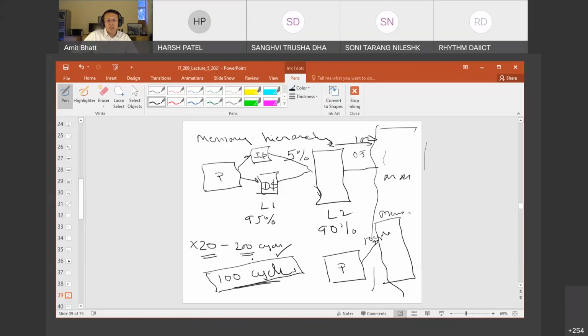So usually real-time processors are embedded processors, right? And then, which programs are going to be executed, they are fixed. For example, in your airbag, the program is fixed that, as soon as you get the signal, you send another signal to these chemical bags, and there is a small explosive charge in that, which would explode. And then it would be filled up with gases, and your airbag would inflate. So in a real-time processor, the programs are fixed. It's like your interrupt handlers. Interrupt handlers are fixed, and you can guarantee how much time they would take. And you can do exact calculation of the latency.